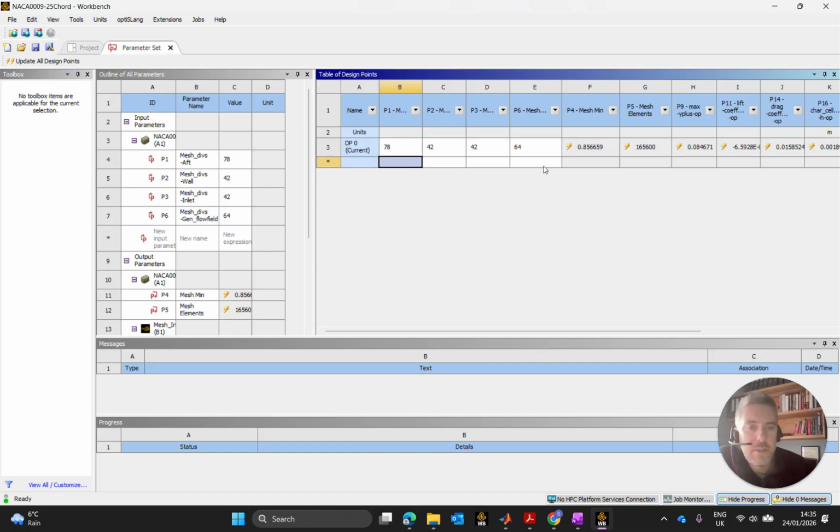As you can see, there are huge spacings there. Minimum spacings, huge spaces between, i.e. large cells, and a few of them. Okay, so I'm going to finish this video here. I'm going to hit stop and we'll come back into the next one. This is going to be our coarse mesh, we're going to set up a medium mesh, and we'll set up a fine mesh from that, the 3 of them. We'll do a grid convergence index study on it for mesh independence and see what we look like at the end. Hopefully we'll not be where we want to be, and we'll have to take it a step further. And we'll see how that takes us.